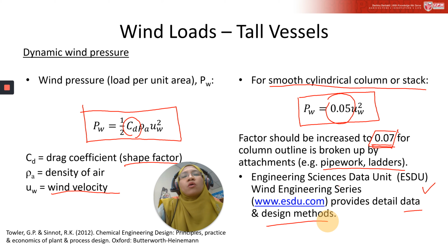So a column must be designed. You must make sure that when you design a column, it is designed to withstand the highest wind speed that may be expected at the site during the life of the plant.